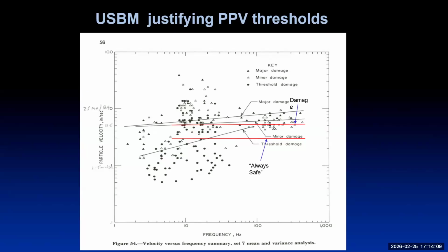There are all sorts of other parameters which went into making up this diagram. When you compare this approach, peak particle velocity within 30 inches of the ground, with what we're telling you about, which is structural dynamics, and looking at that for indications that something is going on in the structure, there really isn't much of a comparison.